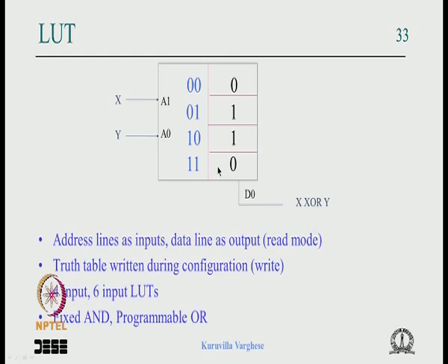The thing to remember is that writing to the memory is done while configuring, and the write control is controlled by the configuration circuitry of the FPGA. As a user you use the memory in read mode, with the address lines connected to the input variables and the data line used as the output. And as I said, in the PROM case it is a fixed AND which consists of all the min terms, and a programmable OR, because this is an AND-OR. We are implementing an OR of this which is programmable.